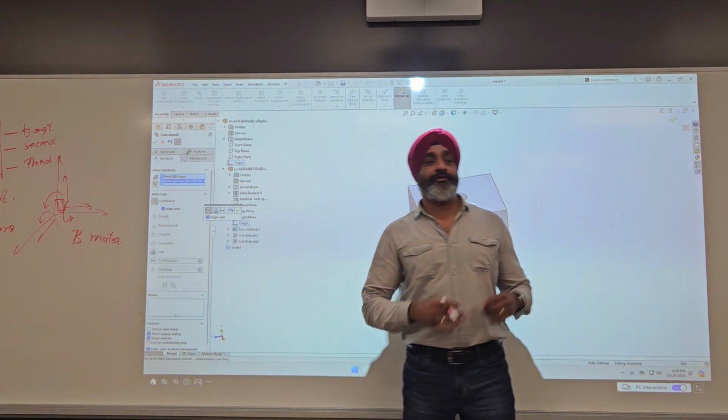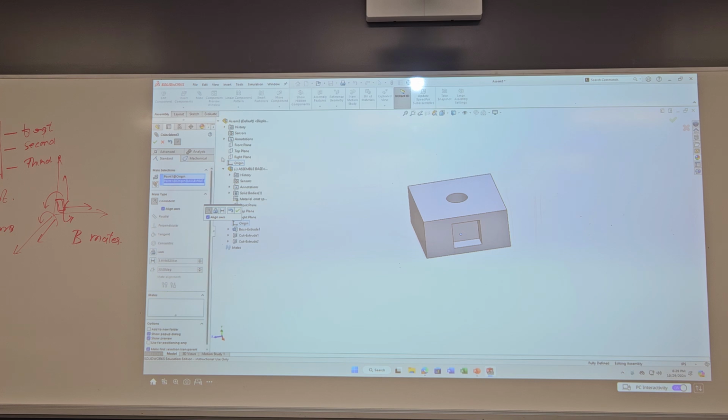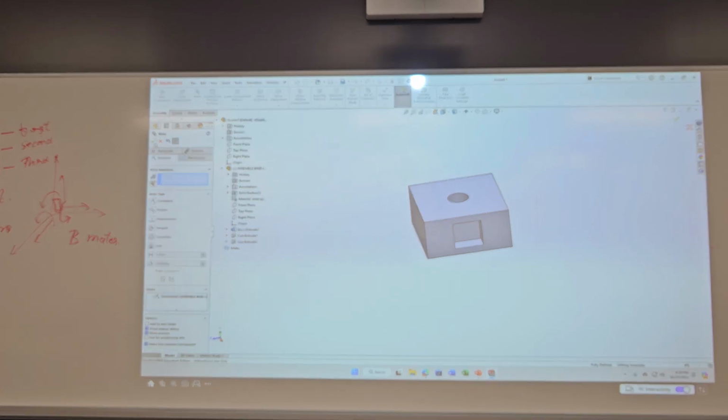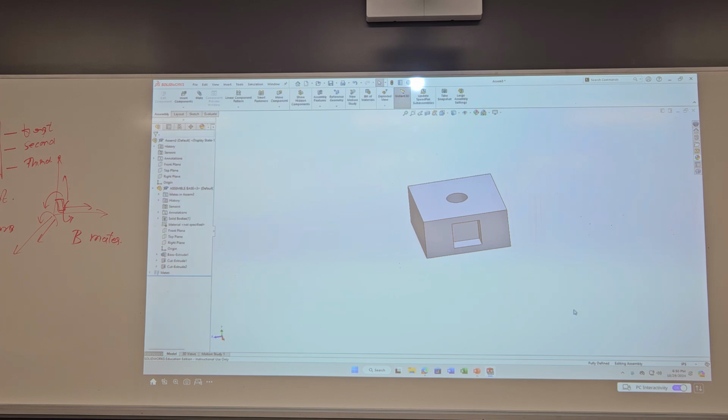But most of the time when you are thinking a design, you're always thinking ahead, so that when you go to the assembly, how they will mate together. Okay, so let's keep it aligned axes, origin to origin, click. It's still, because the mate command, the way it works, you can keep going. You created a mate, yes, it will be available to create the next one. You have to say yes to get out of it. Okay, when you say I'm done mating, I'm out of it.